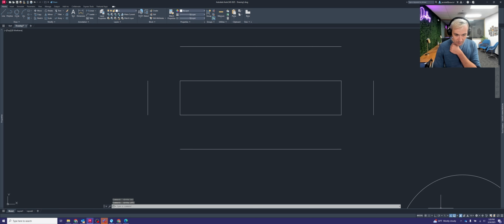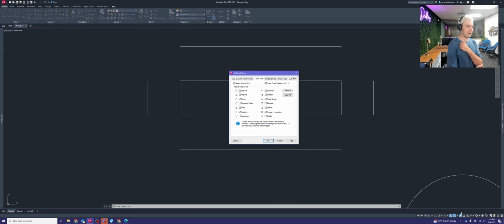I'm skipping over the isometric drawing. We don't really mess with that. I will say, and I will have you pause the video here, this little drop down here is your snaps, your object snaps. So at this point, if you want to go ahead and pause what you're working on. This here is going to be really important. You want to make sure that these are all set exactly the same as what I have here. It's going to help with our training purposes, to make sure that as you're drawing things, they snap the same way as on my screen.